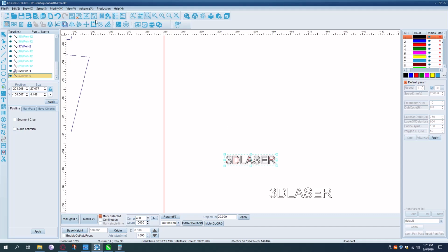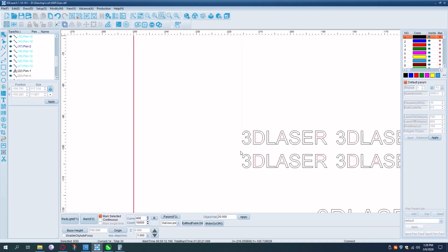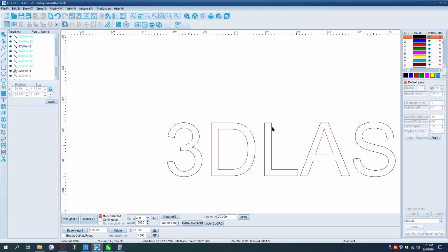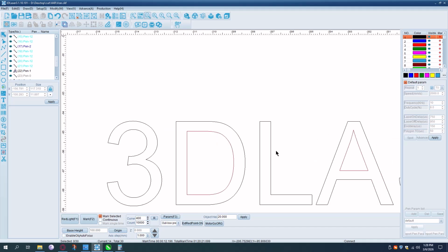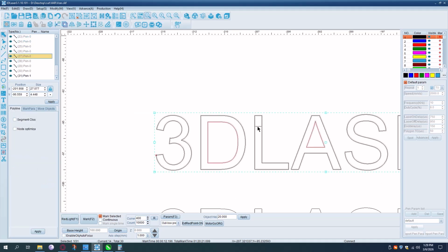When making multiple objects, we can see the object size. And remember, do not use too small objects. The thickness of the object cannot be too small. The cutting size of the laser is a tenth of a millimeter on each side. It takes its form from your object. That's why you need to measure the object.